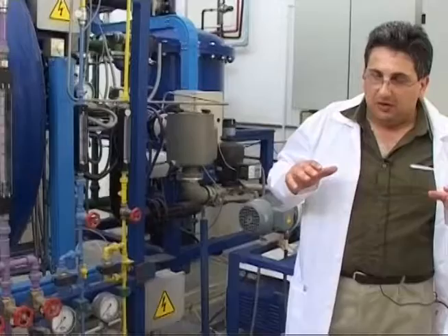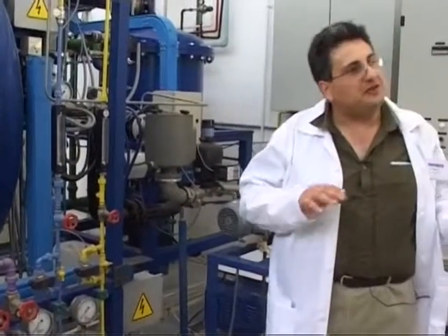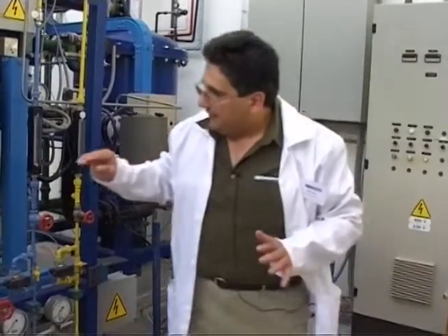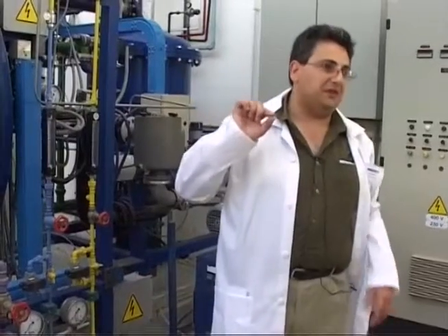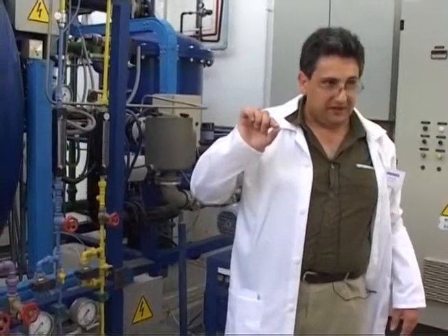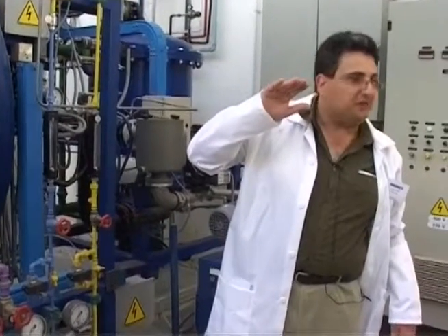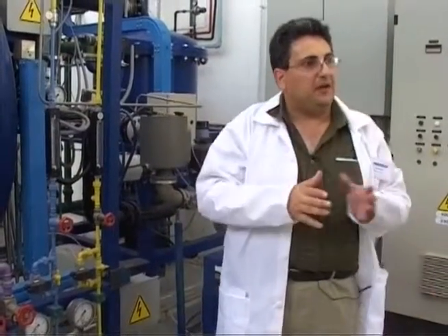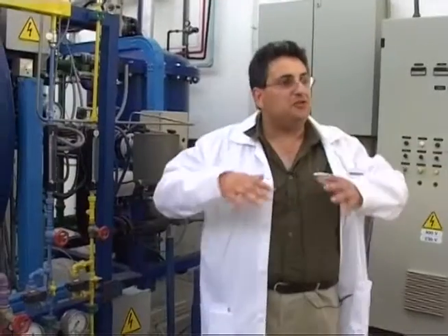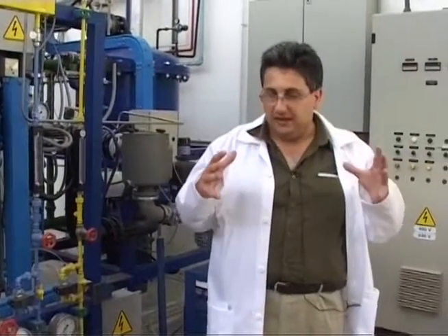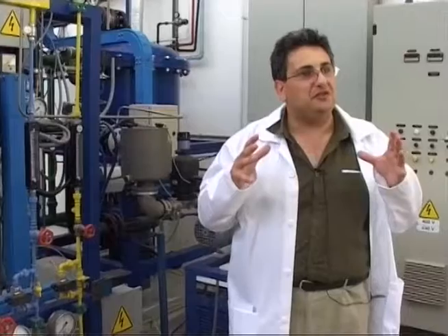The usual procedure is to introduce a relatively high dose of ammonia and operate at a temperature around 520 degrees for a few hours to create a high gradient of nitrogen into the outer surface.